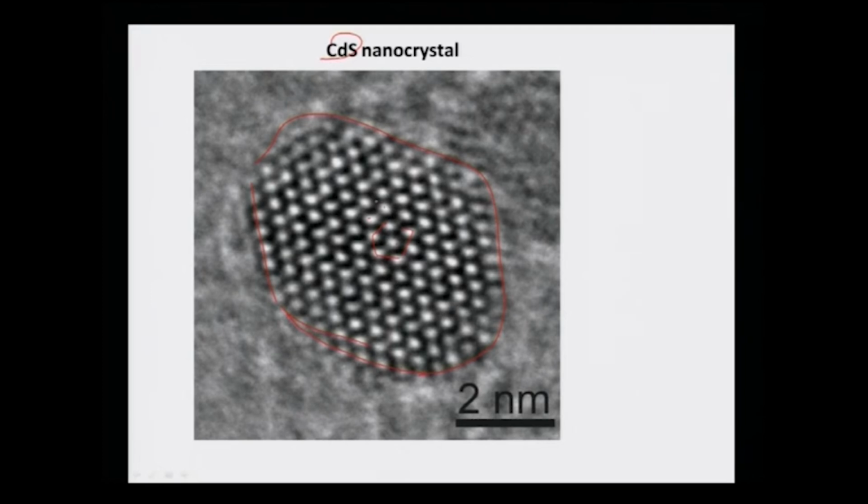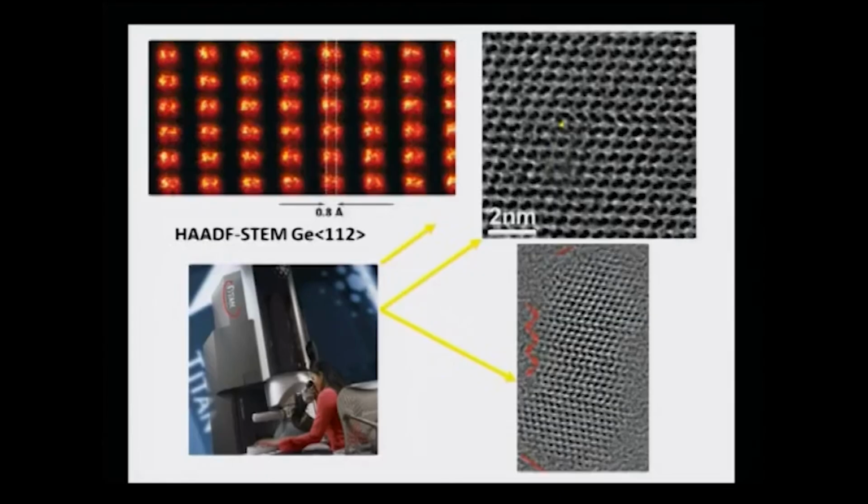It is very difficult to say in normal electron microscopy. But with the advent of the Titan, with new kinds of contrast mechanism, one can tell what kind of atoms are present on the surface by something known as HAADF-STEM, or high angle annular dark field scanning transmission electron microscopy.